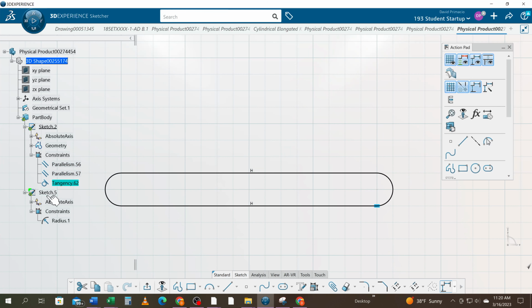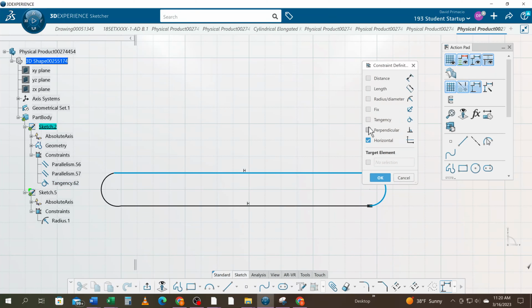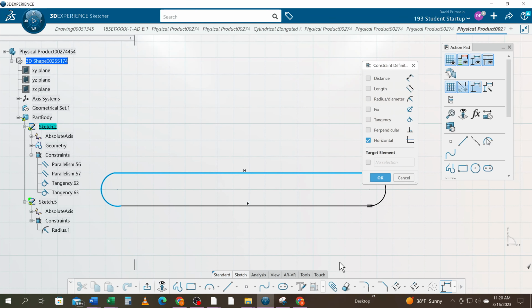Remember, I got to delete that. I forgot to delete that out. Let's go ahead and use the control button to grab this, and then go ahead and use the second box in your constraints to turn on tangency. I don't really have a faster way of doing this, so if someone knows another way, you can show me. But I selected 2 elements using the control button and then apply tangency.